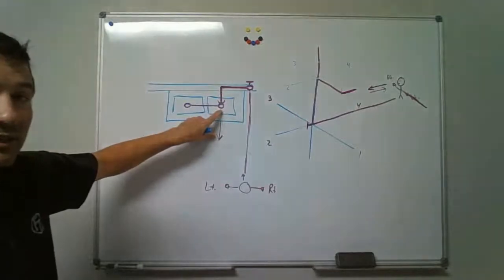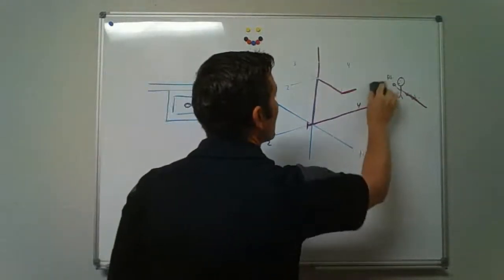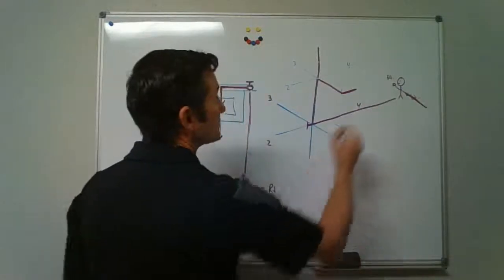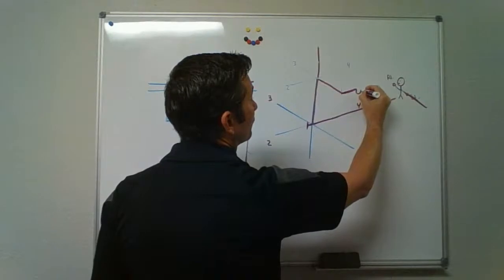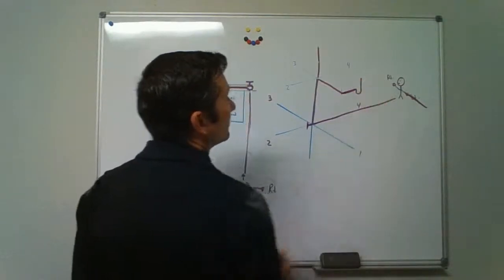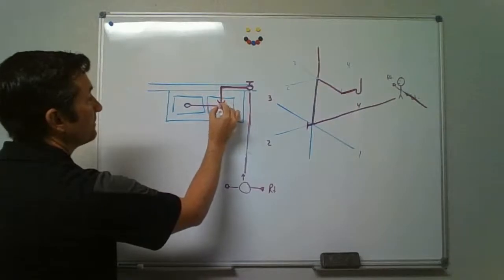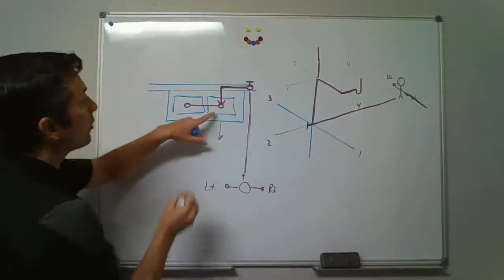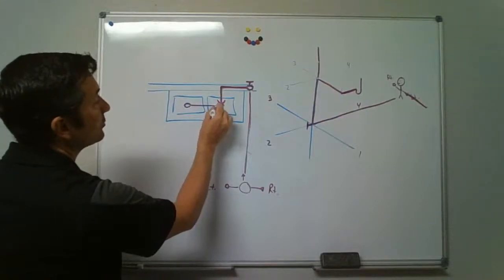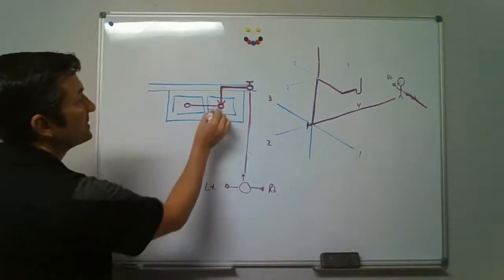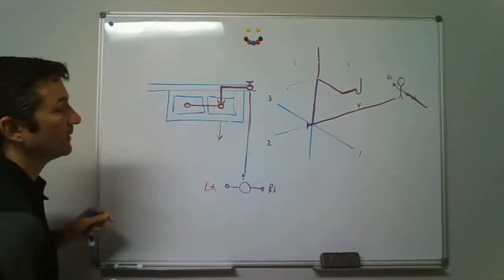What do we have on the end of it? The symbol for a P-trap. So P-traps are drawn straight down, U, and straight back up, okay? You just drew this P-trap. Now, we have a horizontal connection that was going to go from the vertical. See how it's tied to the circle? So that means it's connecting to the vertical pipe, comes over and hits another vertical pipe.